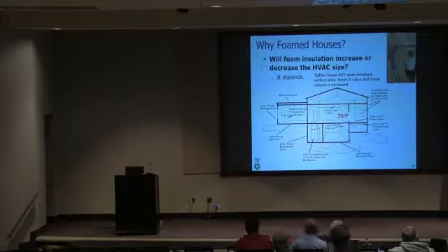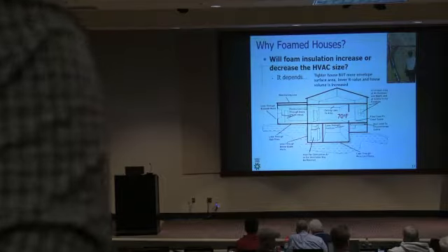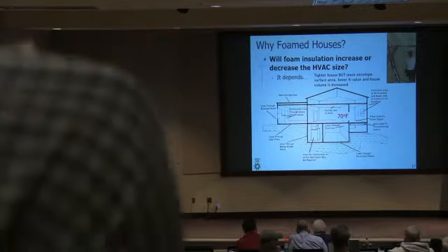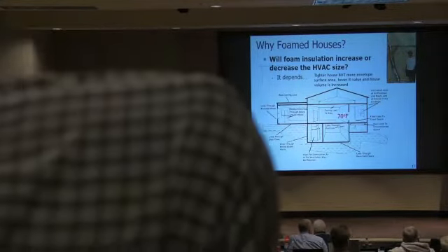So to some extent, you might be better off with your rotted roof decking with a continuous closed cell spray foam under it, because it's structural. So, again, it's a problem that you have to think about, what about roof leaks? But I'm not going to blame my insulation because my roofer did a bad job. I understand it's harder to inspect. That is probably a real issue.